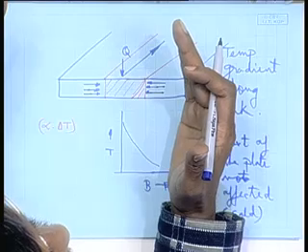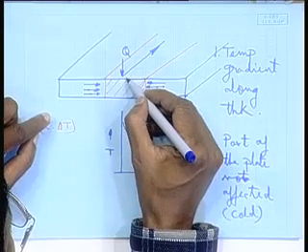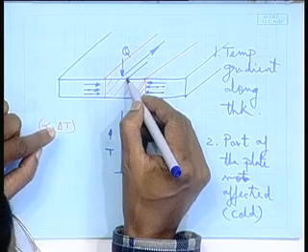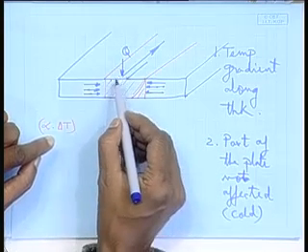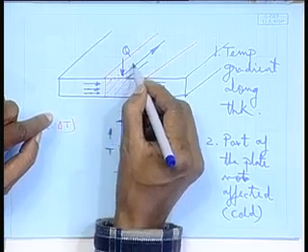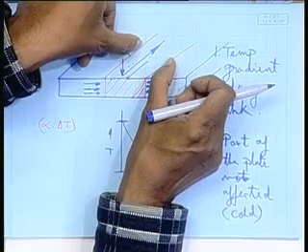Why is shrinkage 0 at the ends? Oh, at the ends, because a transient phenomenon is taking place here. When I start the heating, the maximum temperature is not reached here. If I can monitor the temperature at different places, I will find that beyond a certain place the whole width is heated.